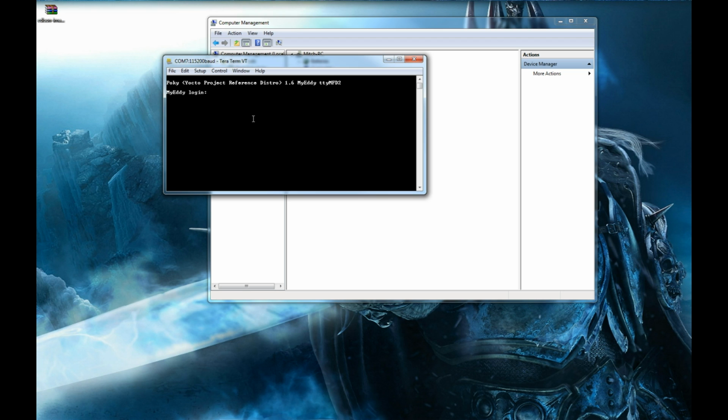I upped the voltage to about 12 volts. I think it's got a 7805 regulator on it. I'd have to hunt around and look for it, but I think it can probably handle up to 30 volts, but don't quote me on it. I would say 12 is probably about max for now, just to be safe. Let's just stay around 12 volts. I'd seen on Intel's website that they used 12 volts in some of their demos. So 12 volts works. I got it to boot up and everything's great. So remember that little tidbit: it does draw quite a bit of energy, and if you don't use a powered USB port, your external power supply needs to be set higher than 5 volts.